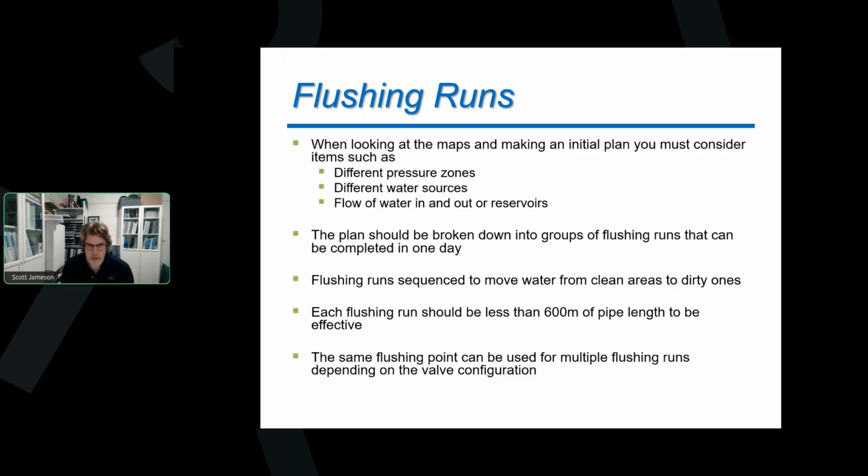If you're doing a run that's a kilometer long, that debris you're picking up has so much time to get caught in an elbow, caught in a bend. We just need to carry it so far to get out of the pipe that it might not be effective for us. So once again, we want to keep those runs reasonably short.